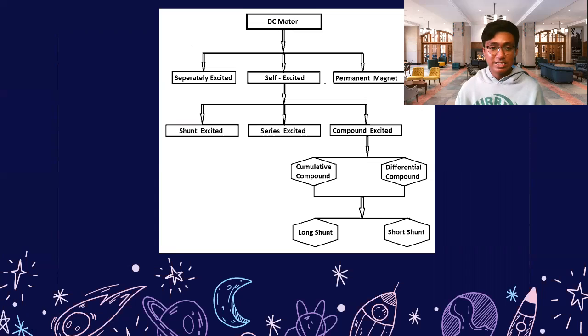Next is the series DC motor. In the series DC motor, the field is wound with a few turns of thick wire carrying the full armature current. Typically, a series DC motor creates a large amount of starting torque but cannot regulate speed and can even be damaged by running with no load. This limitation means that they are not a good option for variable speed drive applications. That means the series DC motor is not suitable for use in a variable speed drive like an RC car control.